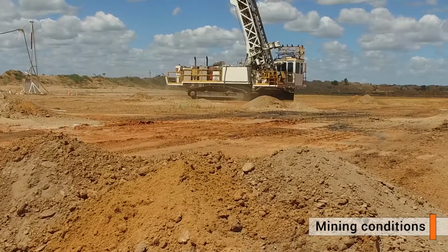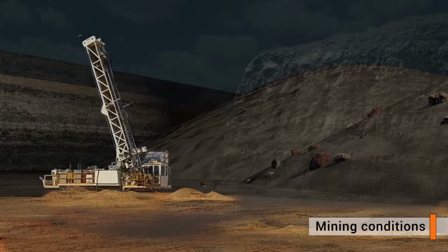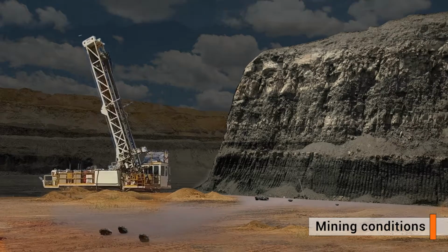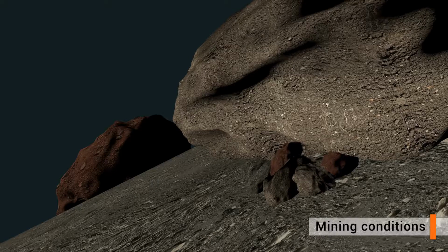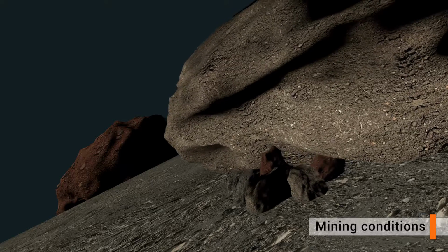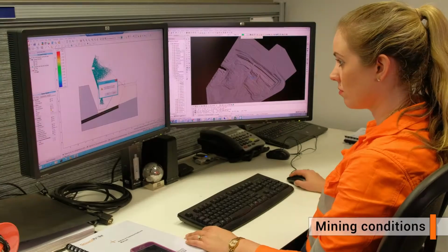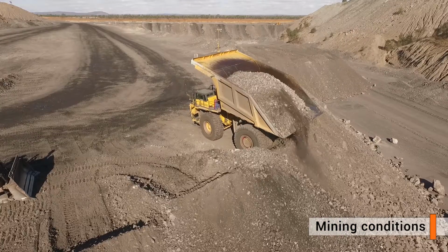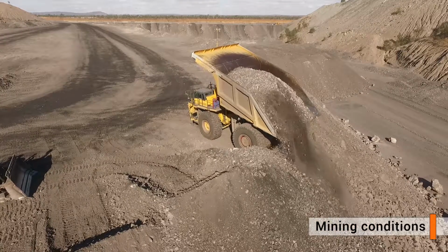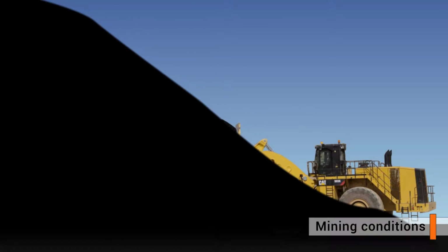Drilling or tramming of equipment next to or in the vicinity of freshly dumped waste slopes, coal stockpiles or excavated slopes that exhibit a jagged face with loose rocks or blocks in the face. Vibrations can result in a rapid loss of cohesion of dumped slopes or coal stockpiles, or cause loose rocks to dislodge in rapid time. And deviating from the mine design without geotechnical review. For example, dumping or excavating past designated surveyed control limits, or oversteepening or undercutting design slope batter angles.